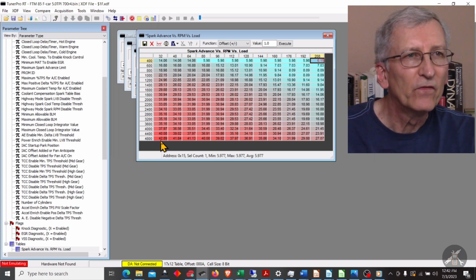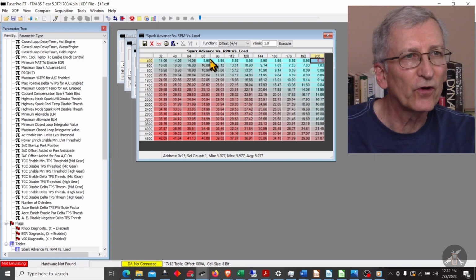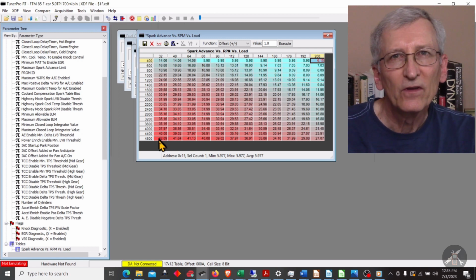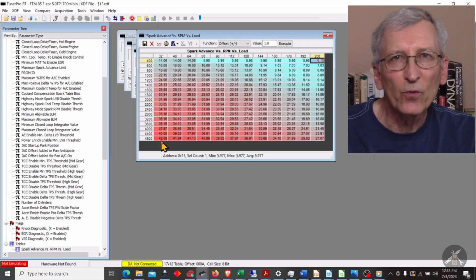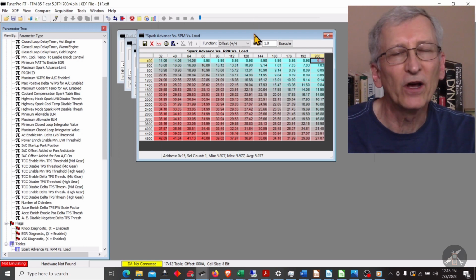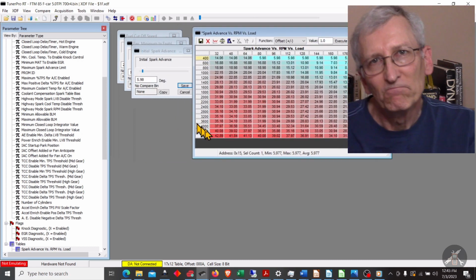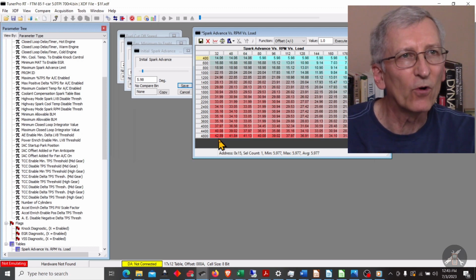They're assuming that your initial advance is 6, and so then this is your total advance, assuming that that's at 6. If for some reason you set this at 0, then the computer wouldn't know any different. It would think it's putting out 42 degrees, but you'd be 6 degrees short. So you kind of want to work those things in and make that work.